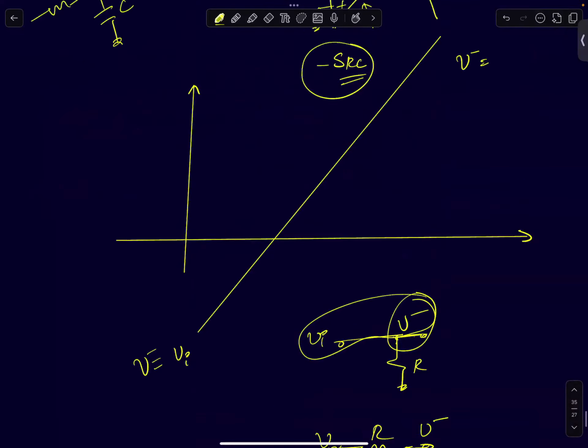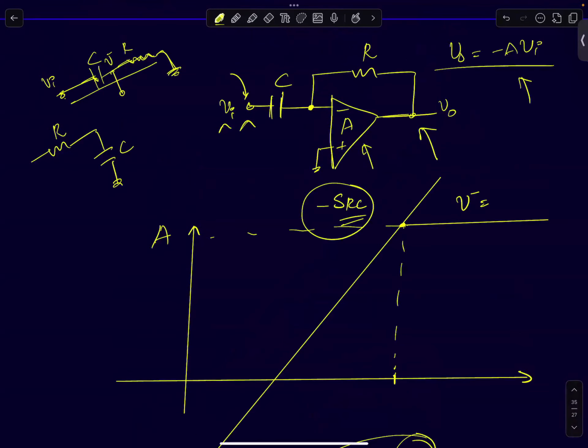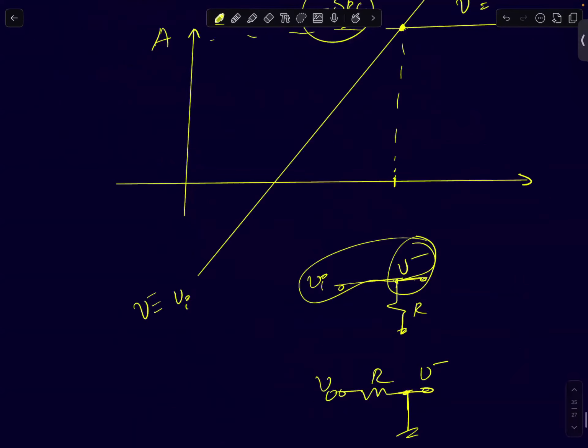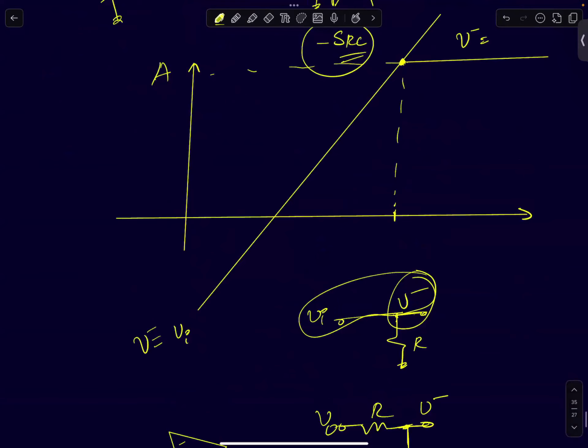So that's it. All I'm trying to say is the gain will saturate at some point to a value of A. And the point of transition, you can figure that out by equating these two. Can you derive that using this very simple intuition? We can use the Miller effect, I'll tell you using the Miller effect too, but you can also use some very simple intuitions.